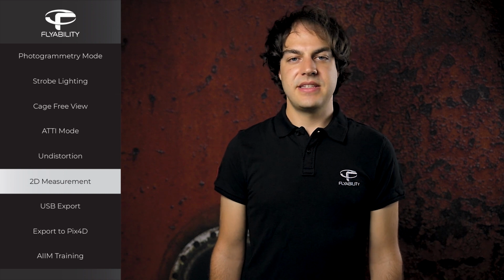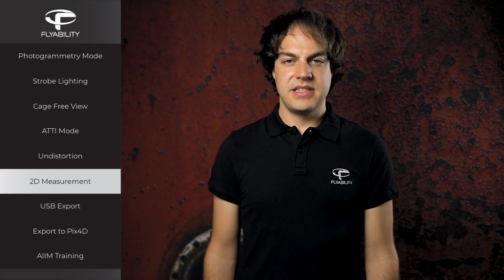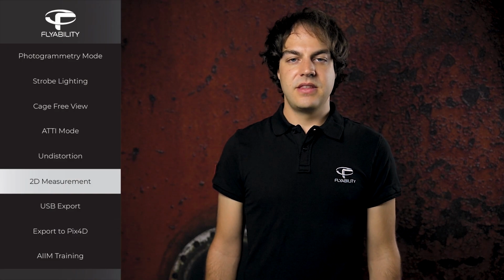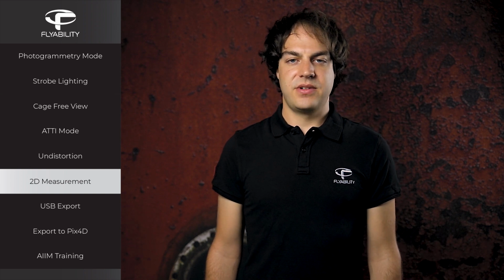Taking advantage of the distance sensor mounted next to the camera of Helios 2, Inspector knows the distance between the drone and the object of scrutiny. Using this information, Inspector can estimate the distance between 2 pixels in the image. When looking at the point of interest, click any 2 points in the image and Inspector will measure the distance between the 2 points and give you an error estimate. To get the best results, your drone should be perpendicular to a flat surface.